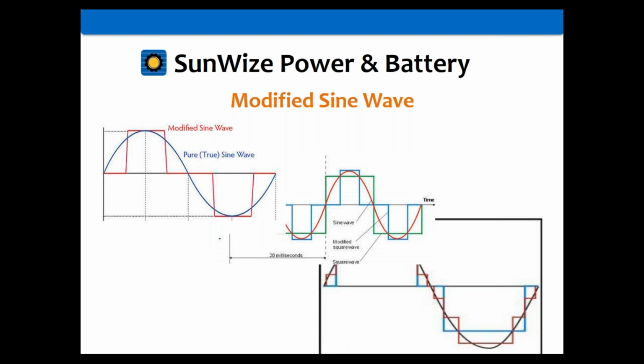That may cause the coils in your motor to heat up, and it may cause it to overheat or operate inefficiently. So I'm not saying that modified sine waves are bad. I'm just saying you need to make certain that it's not a problem for your load, whatever your load may be. If you're not certain, I would advise always just using a pure sine wave. That way there's never an issue.